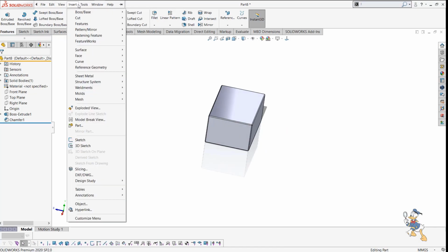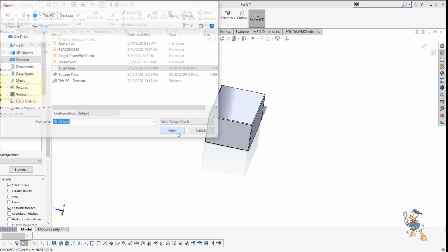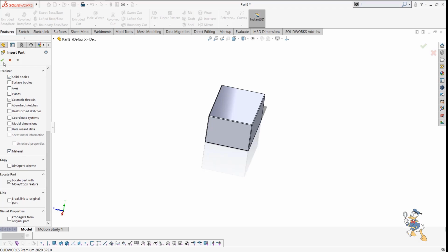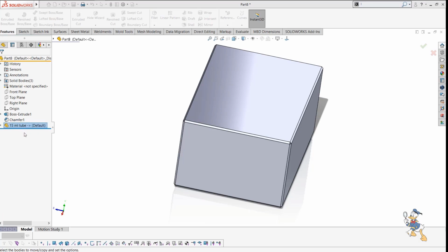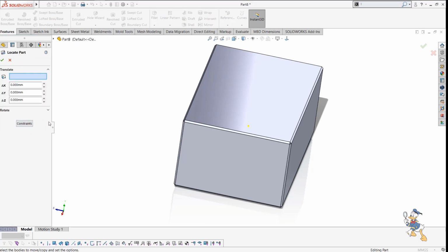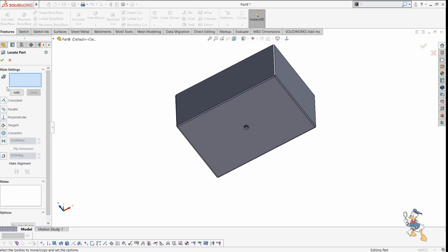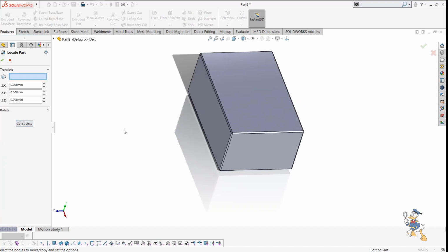And suppose I need to generate holes related to that plastic body which I have just designed. So I just need to insert that plastic component. It is also a multi-body design facility available in SolidWorks, where we can select any other part as well and insert it into our body, and by locating that body in the feature, we just need to provide some values. Suppose I need to move it to the upper side of the body, so I move it along Y.